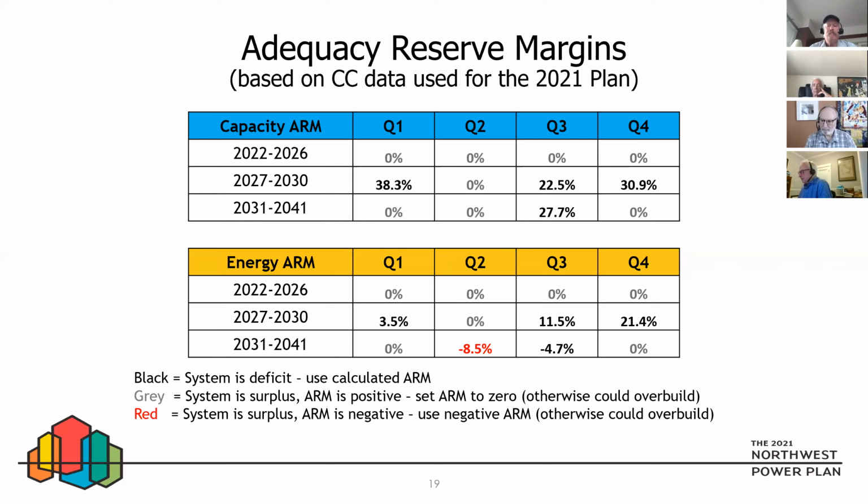And in the summer, we allow no spot market, but we do also allow for what we call purchase ahead. These are imports that are only available during the off-peak hours, which would be like from, I think, 10 o'clock until 6 in the morning, or something like that. And they only happen not during an hour of need, but they only happen if the model anticipates there might be a shortfall either in the next day or the next week. And so the model would import power during the night and use that to replace hydro generation and keep the water behind the reservoirs, so that we would have additional peaking capability during the peak hours of the next day. And so that's what we assume.